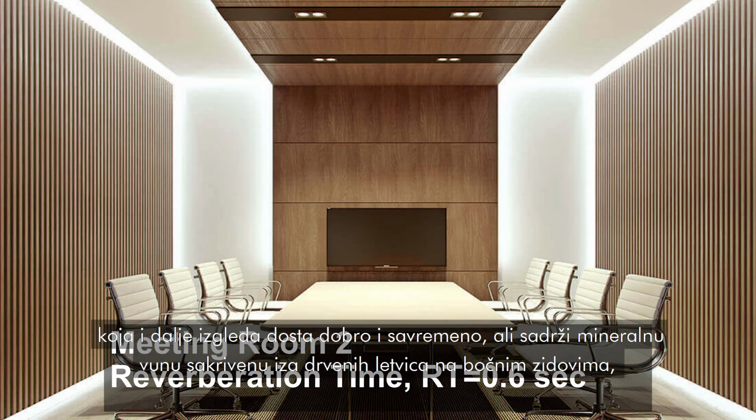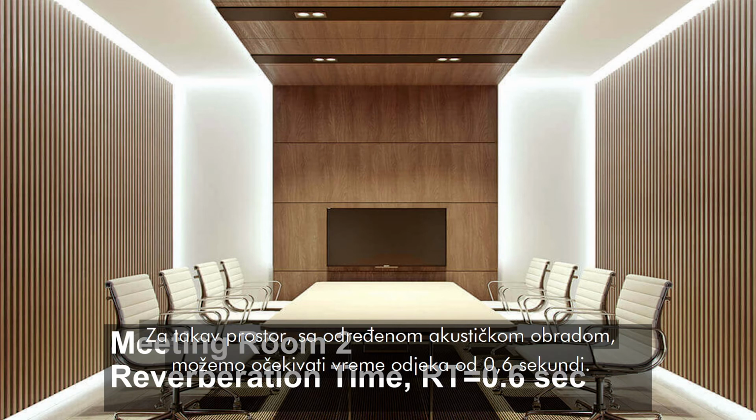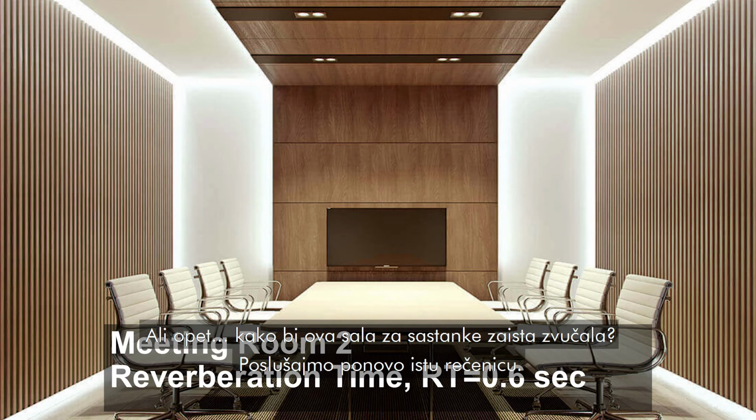This one still looks good and modern, but unlike the first one, it incorporates some mineral wool which is hidden behind these wooden slats on the side walls, and it has some mineral wool above the micro-perforated wooden ceiling panels. So for this space, with some acoustic treatment, we would expect a reverberation time of 0.6 seconds. But again, how would this meeting room actually sound? So now let's listen again to that same sentence.